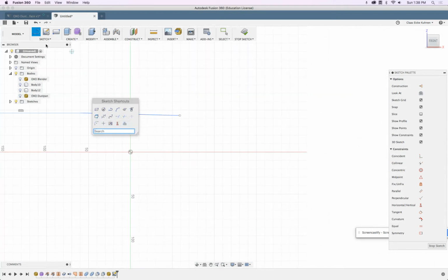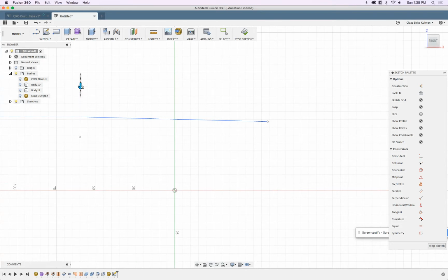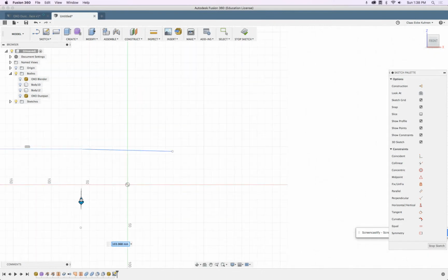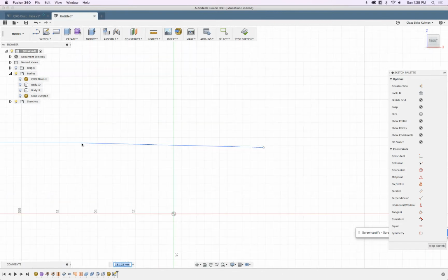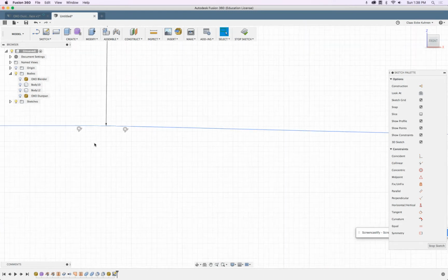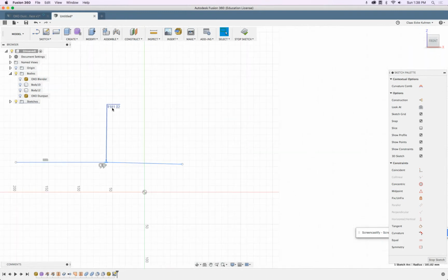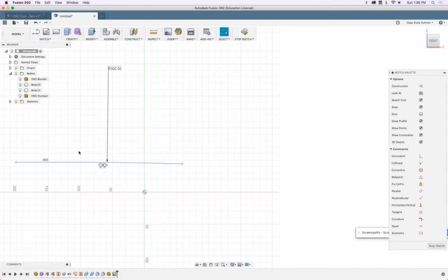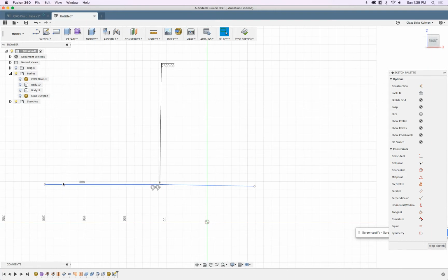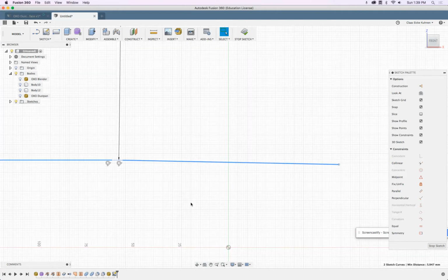Then go to sketch and fillet. You see this line and this line. I would like to fillet. Whoa. Fillet more. Okay, enter. There is that fillet. So it's radius, what about 250? 300? Yeah, okay. So this fillet basically creates a nice transition between these two lines.